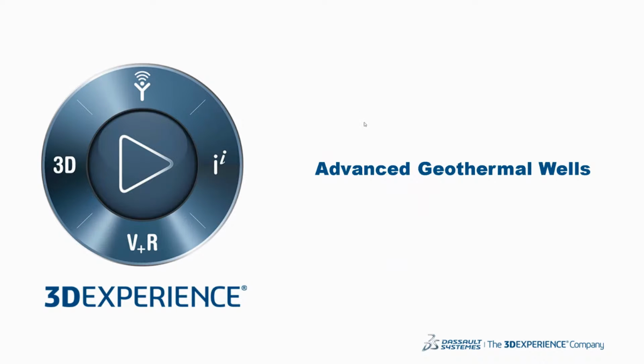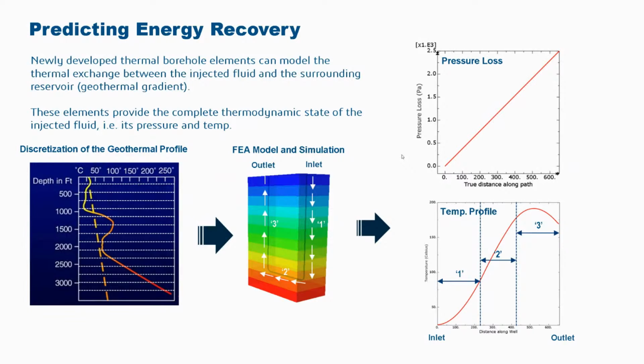So I'm gonna next show some examples of advanced geothermal wells. In advanced geothermal wells, basically you have what we call a subsurface loop that runs through the depth of the earth. Typically you have an inlet well and an outlet well, and these two wells are connected by what we call a lateral section. You inject the fluid from the inlet section and you produce the fluid from the outlet section.